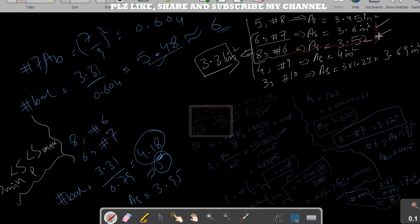Always choose the closest one, because a larger area of steel affects the epsilon t value, right? It affects the epsilon t value, and in that case our criteria, which is greater than 0.005, is unsatisfied, right?